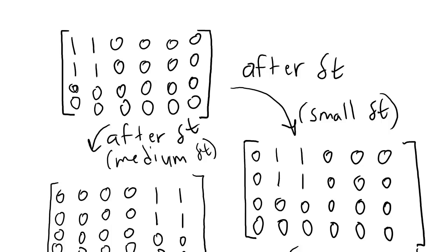One of the reasons that this is important to keep in mind is because one of the applications of motion detection is motion tracking. For example, we may want to have something rotating and pointing at the object that's moving while this happens. The slower or lower our sampling rate is detecting the motion, the more difficult it will be to be able to control the motion of the thing that is rotating towards the thing that is moving during this time. We would like to set delta t in such a way that we can brightly capture this motion and also get as many samples as possible as the object moves across the screen. Let's take a look at how we might estimate a good value of delta t.